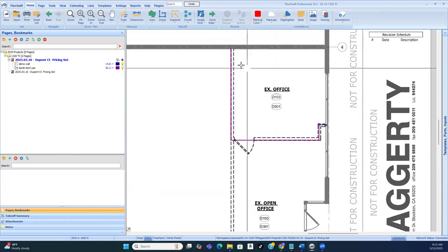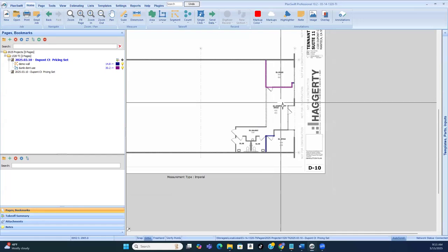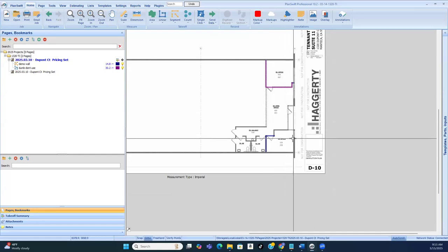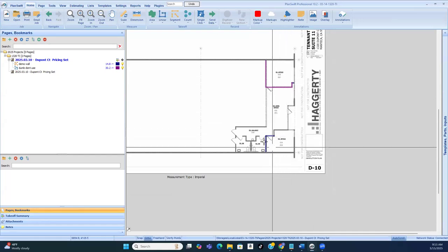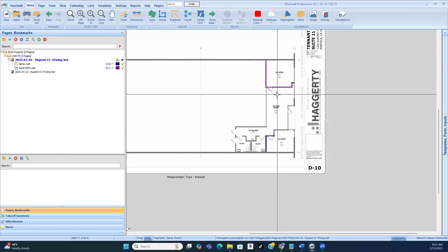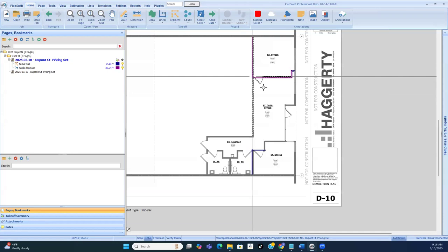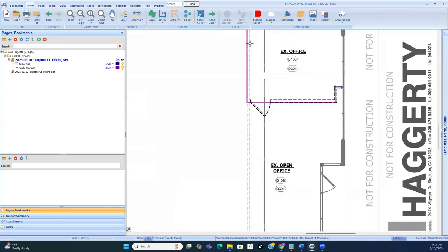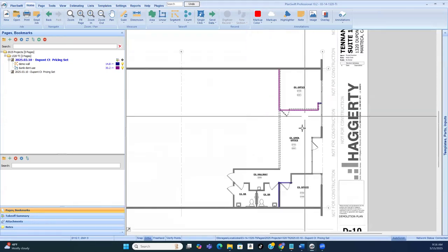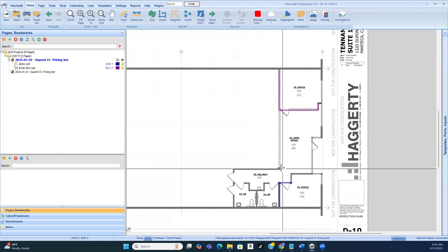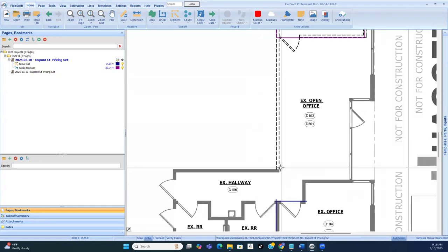You figure out how many linear feet of wall in general you have to demo, and use that standard for all of it. And assume it's light metal. They aren't telling you, because that makes a difference. I give myself the benefit of the doubt. I assume they're all 6 inch. It's not a house. I'm assuming it's all 6 inch metal framing.